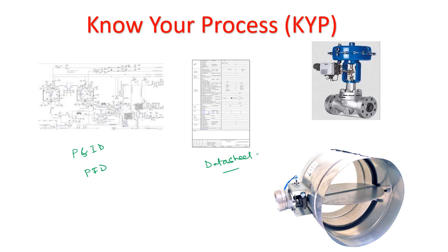And in some cases, it makes sense if you visit the site also. Sometimes what happens is that these control valves are there for years after years and they are in a degraded condition, right? So even if you tune the loop, you will not be able to tune the loop properly with a degraded control valve.